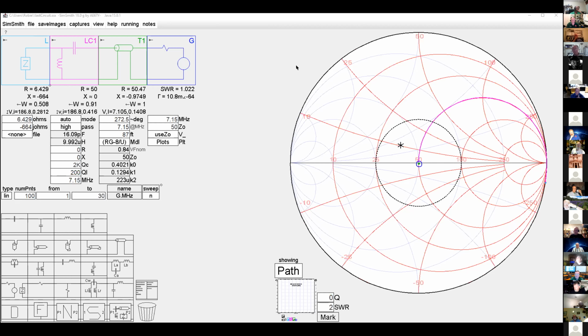But we have plenty of experience, Keith, to know that off-center fed antennas are inherently imbalanced, and they're prone to a lot of problems with common mode currents on the outside of the transmission line, not on the inside. I'm not saying they don't work, because they do work, but that's just one of the negatives you have to live with. So I would try a good common mode choke, and you may have to put two. You may have to put one up at the top, and one further down on the transmission line. But I think you can knock it out to something that you can live with.